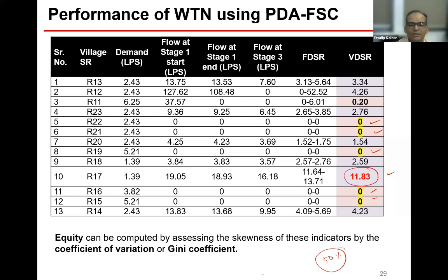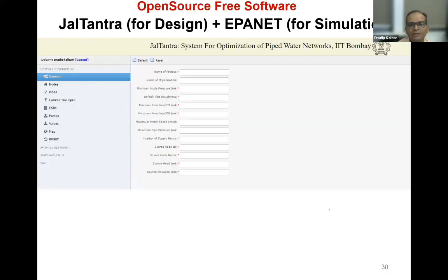I'm not saying that this particular modeling approach will give you the exact behavior, but this is an initial understanding of the system, which our current methods do not give you, because those assume a different scenario than the actual one on the ground. So this particular method allows you to incorporate the actual behavior of the system. So use this 50% of the knowledge and then 50% on field. So a lot of field work we have to do. We have to monitor the pressure, we have to monitor the flows in the network, and then decide on the intervention. Some of these things we'll discuss.